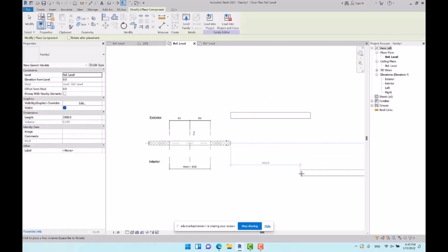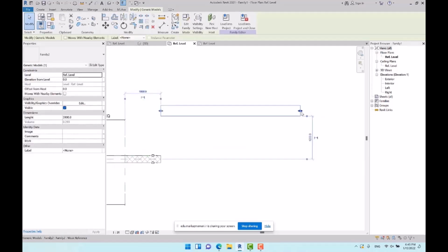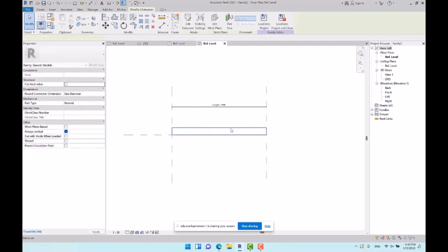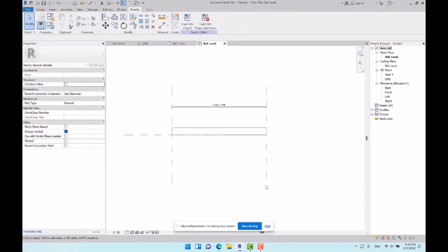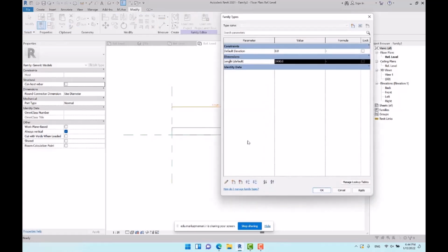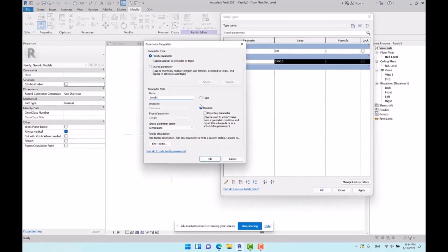Right now, as you can see, we got the shape handles to control the stretchiness or the length of the profile. So here we learned that when we are modeling a family, if we associate the parameter to the sketch itself or to the geometry, we get no shape handles. But if we associate the parameter to the sketched reference planes and then connect the object or geometry to the reference planes and then associate the parameter, we will be given the shape handles for controlling the length.